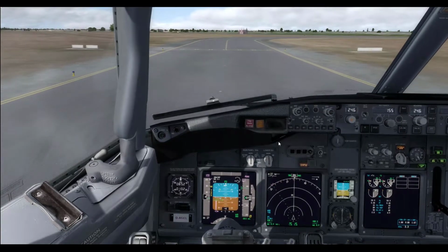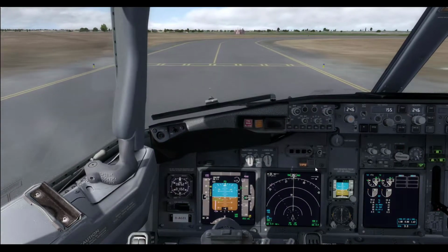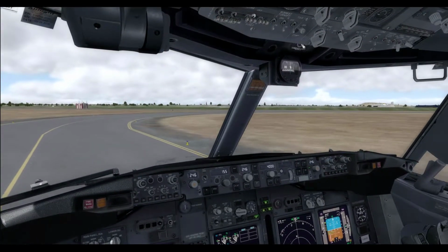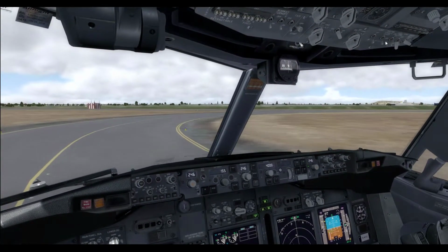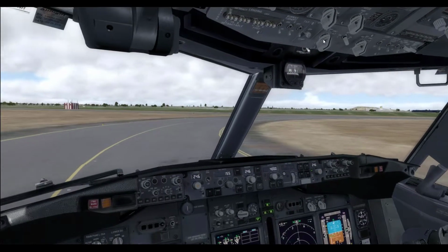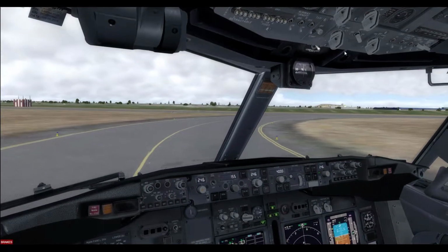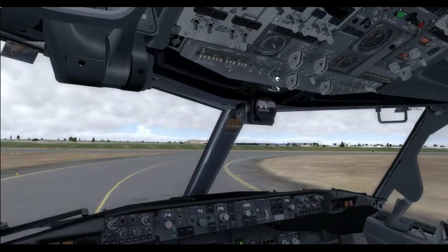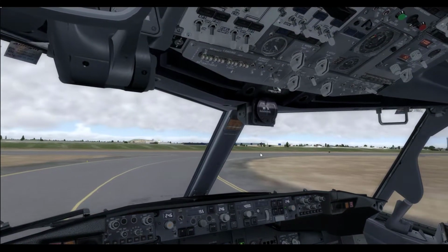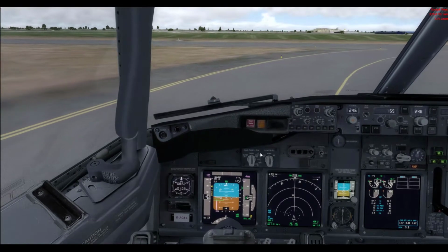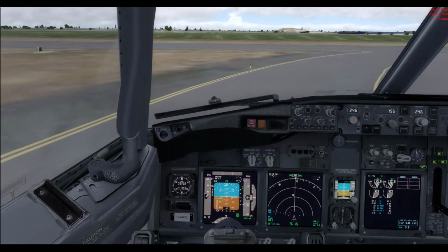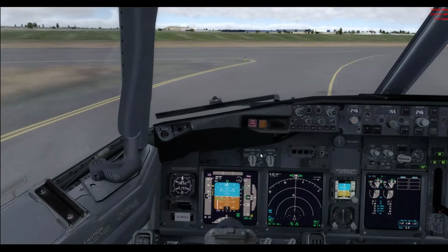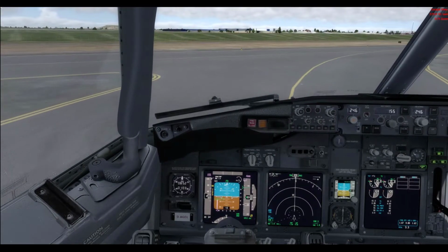Now, we will retract the flaps, put the auto brake off, stow the speed brake, landing lights off, strobe lights off, wing lights off, put the engine start switches back to continuous, and we will start the APU. You remember that from the first part, how you do that. Now let me just take that turn without actually screwing it.